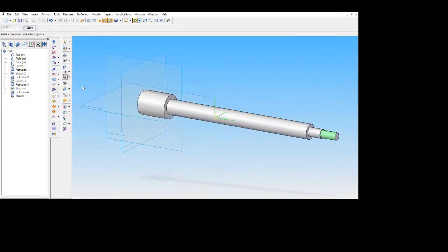Now again the thread should be formed on this part of the protruded surface. Select this protrusion number 2, select this end part. Now we have to make a protrusion only till the finite extent. Give the finite value option and select the distance of 170, and the type of thread is TR 20 into 2. Click finish.